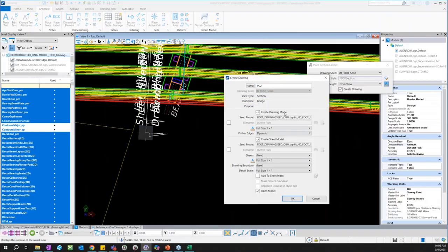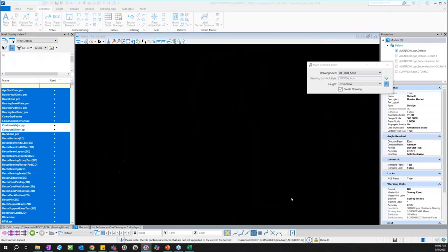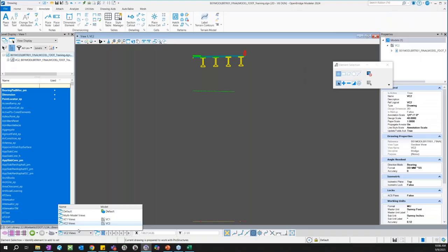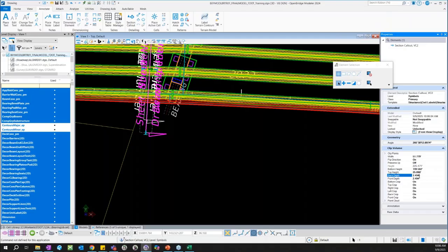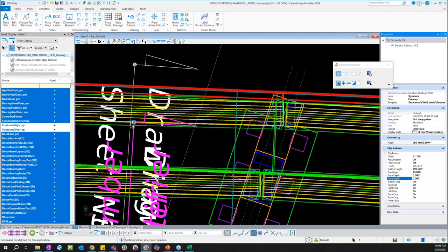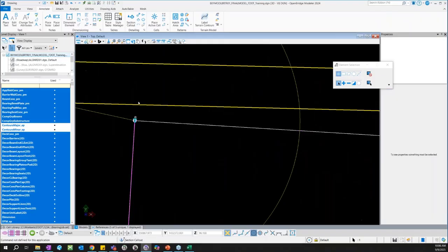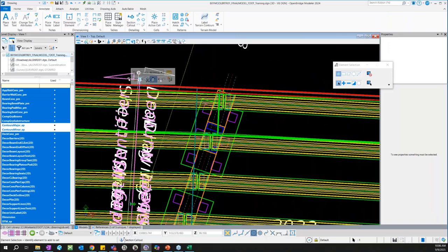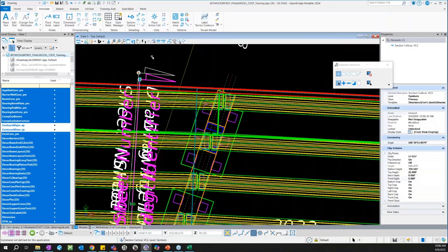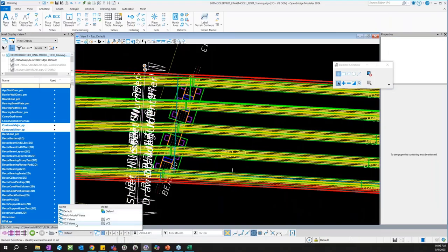We'll call this vertical clearance 2. The same. We don't need a sheet, so it's going to create now just another drawing model here. So we now have VC1, VC2. I'll go back to the default model and make those same adjustments. We don't need any depth to this section call out. Just have it be 0. And then again, we don't necessarily want it to end right there. We can have it continue. So we'll pull this out, it keeps flipping that on me. Right click, flip direction, just so I don't get disoriented.